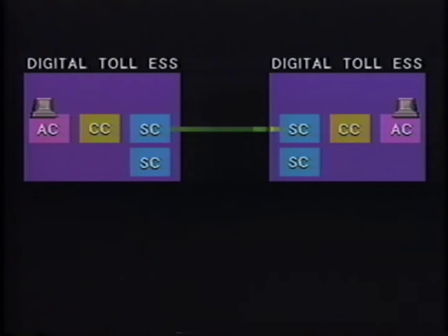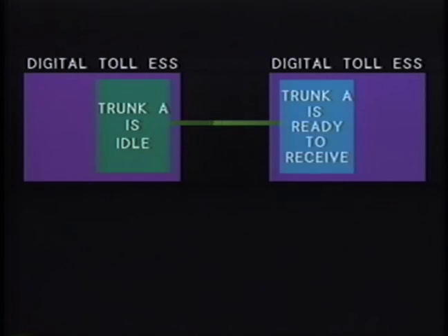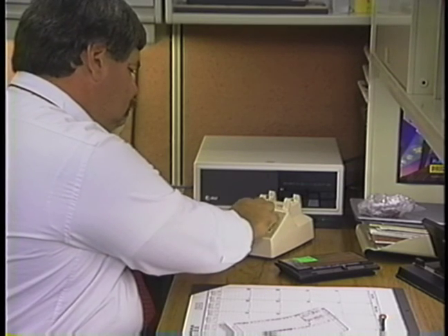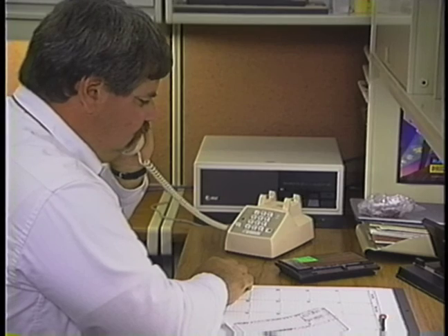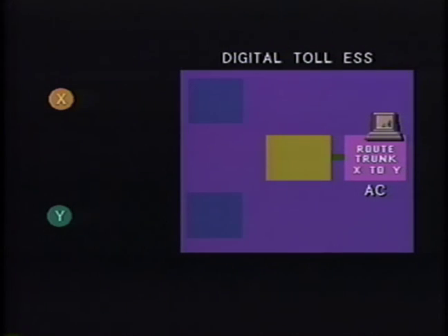Therefore, the digital toll switch isn't equipped for many of the functions relating to customer lines, such as ringing and dial tone generation and other customer line signaling. The digital toll electronic switch performs call processing functions between inter-office trunks. For instance, trunk scanners monitor the availability of trunks connected to the toll office. If no trunks are available, the digital toll switch sends an all circuits busy message to the originating office, which transfers the message to the customer's line. This is the only status indicator generated by the digital toll switch.